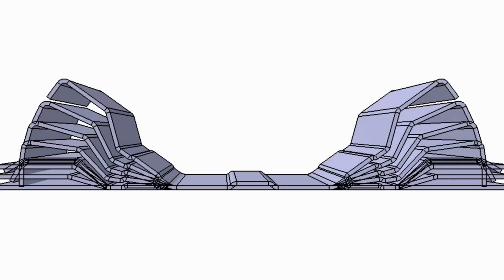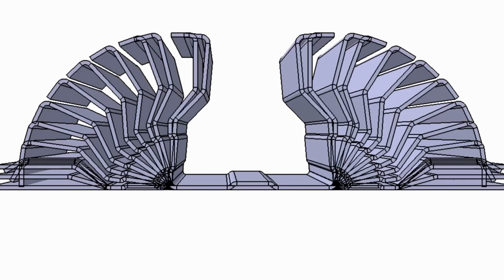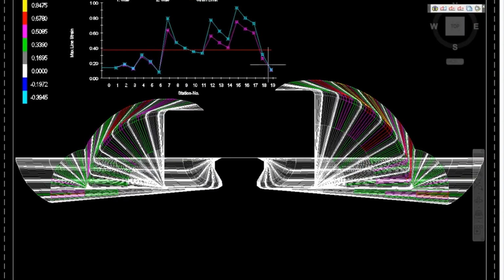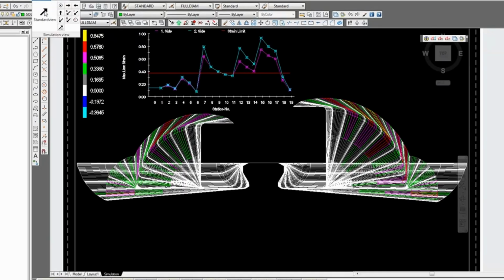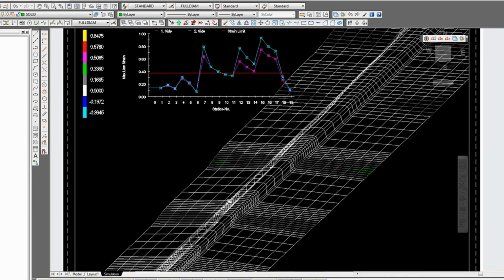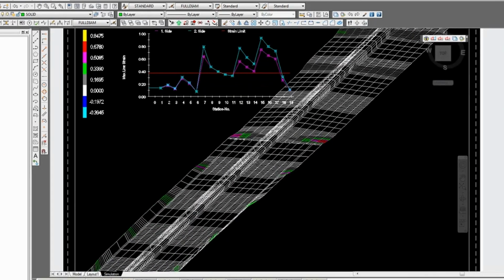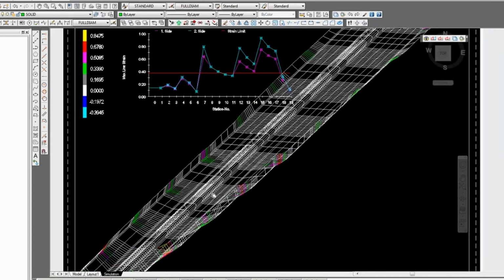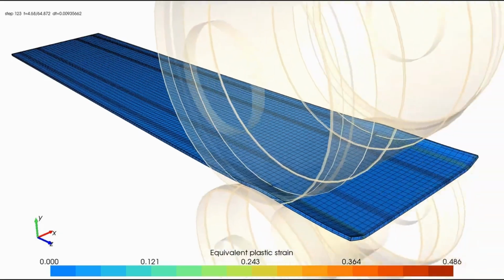The necessary knowledge is taken from a database that is constantly updated as the system is used. When a new profile needs to be designed, a similar profile from a previous project that was successfully produced is usually used. The flower pattern and roller tools are modified according to the shape of the new profile. The results can be verified using quality management tools, calculation of the stress at the edge of the strip, analysis of the stress of the profile, or the virtual machine for roller forming, which simulates the process of roller forming using the finite element method.